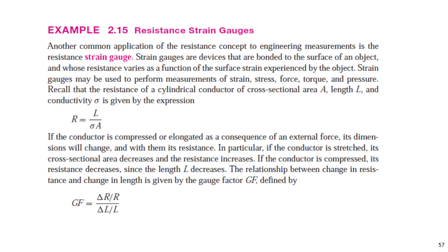Maybe under the floor of an elevator, we put a strain gauge under the floor. When the weight is over the capacity of the elevator, it will send the alarm. We can measure the weight. If too many people get in the elevator, what happens? The elevator will sound an alarm, sent by this type of sensor. Its output is in ohms, in resistance.